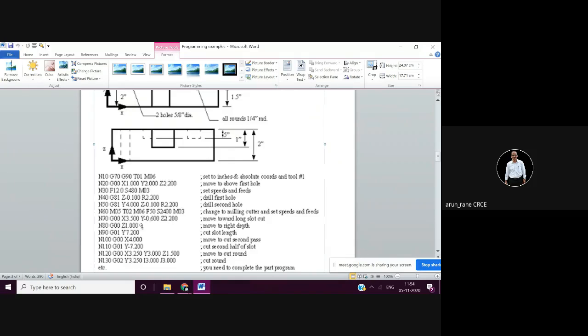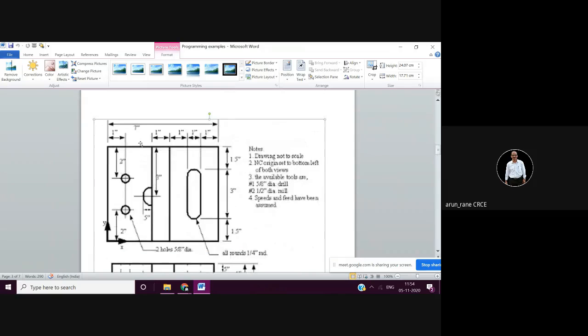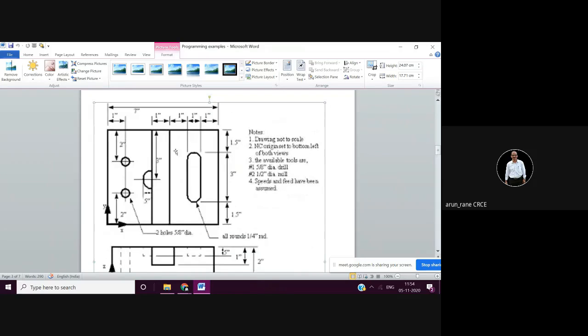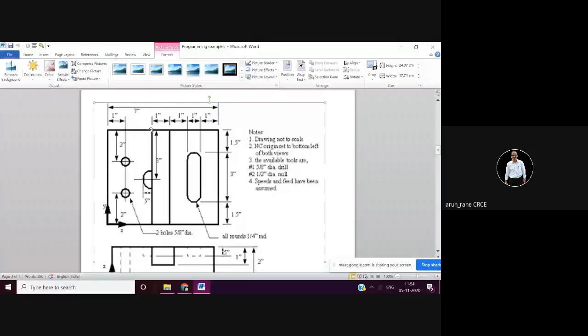So now let us see which one is tool number 2. Now how to debug. So G00 X is 3.5 inch. Where will 3.5 inch come? This is 7 inch, and after that, how much is this, 1, 2, 3, 4, so this distance is 3 inch. The width of this is 1 inch, so its half will be 0.5.